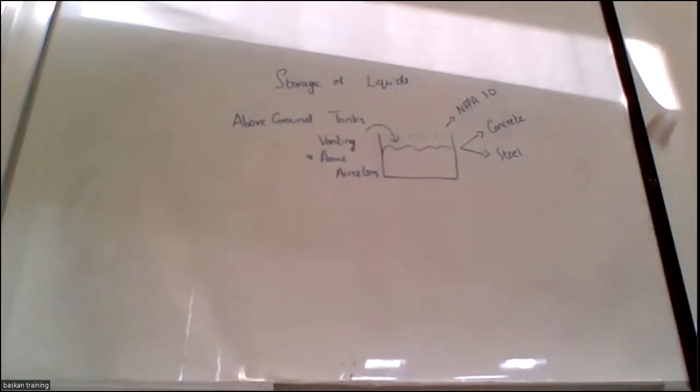The pressure at which the hose and nozzle dispense the liquid accumulates static charges, and these electrostatic charges can create a spark if they exceed the threshold limit of the material. That spark may start a flame with a flammable liquid or flammable vapor.